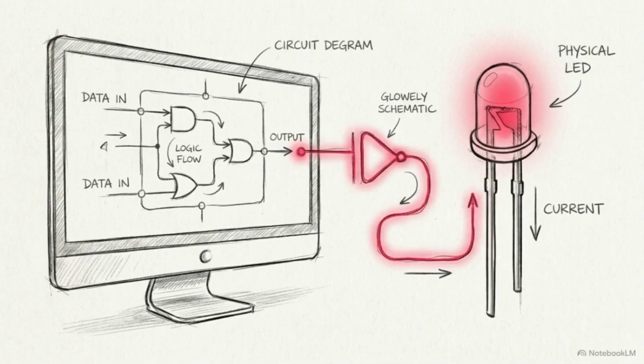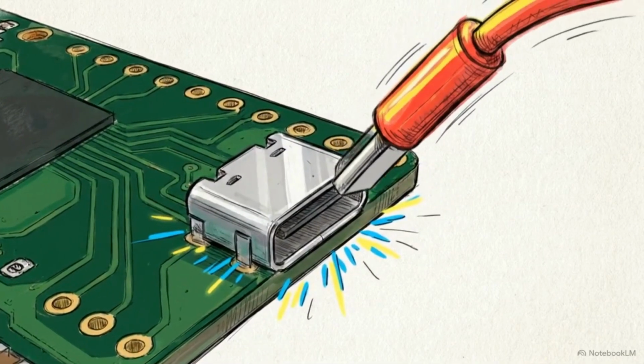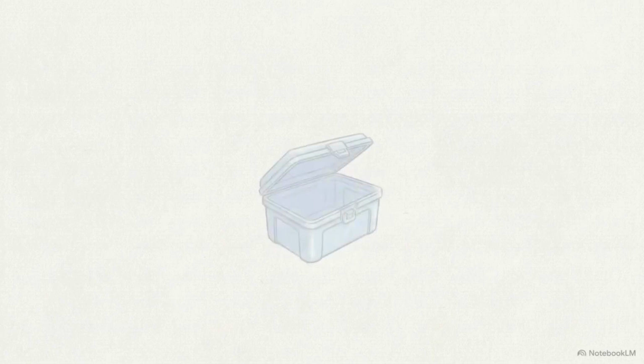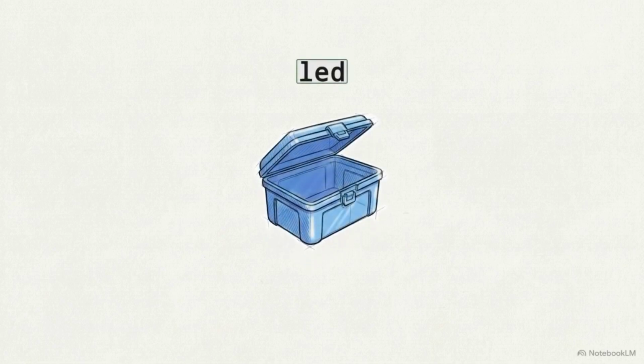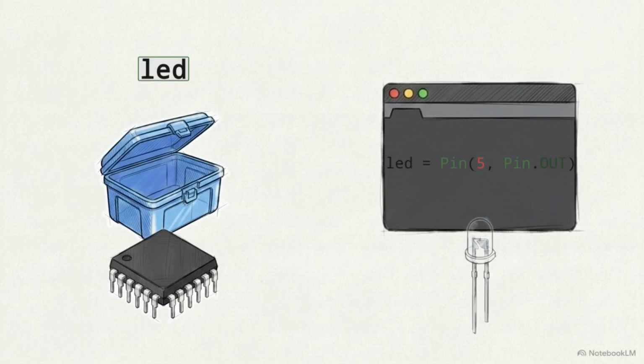actions. Now that the board can operate its pins, we need to give our LED connection a clear label so we can reference it easily. To do this, we use a variable. Think of it as a container, much like a lunchbox. Let's create ours. Type led = Pin(5, Pin.OUT). The number 5 maps directly to the physical wire connection we looked at earlier.